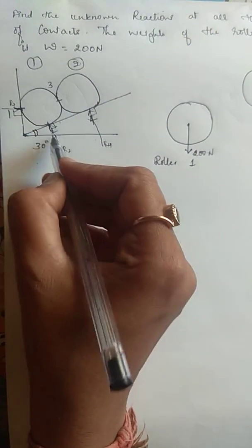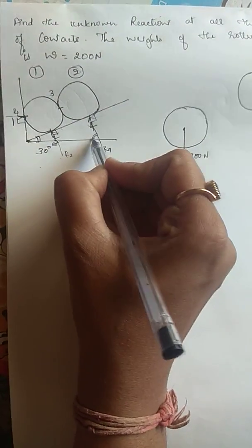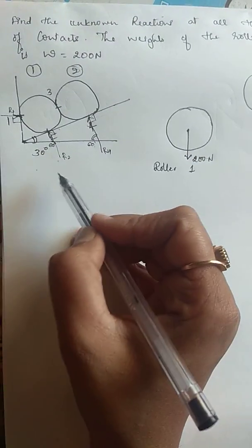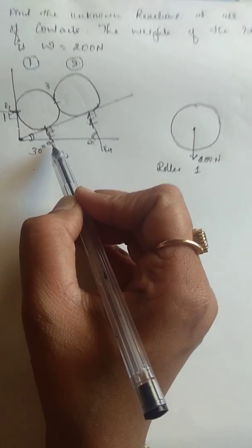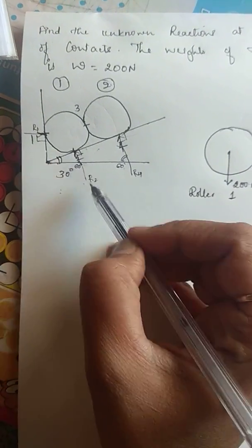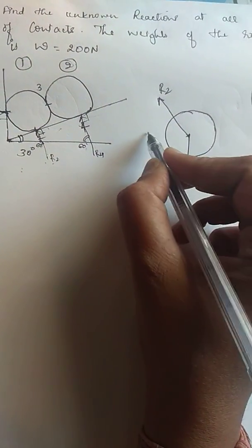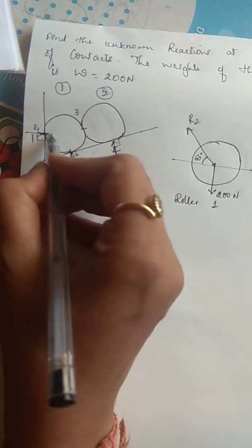So in this particular given triangle, if this is 30 degrees and this is 90, this would be 60 degrees. Similarly, this also would be 60 degrees. So I'll have reactions R2 and R4 which make an angle of 60 with the horizontal. So getting back to this roller, I'll have to show its weight, reaction R2 and reaction R1 along with R3. So we have a weight coming downwards, then I show R2, going like this. We found that R2 makes an angle of 60, so this is 60 degrees. I have R1 which is horizontal force.